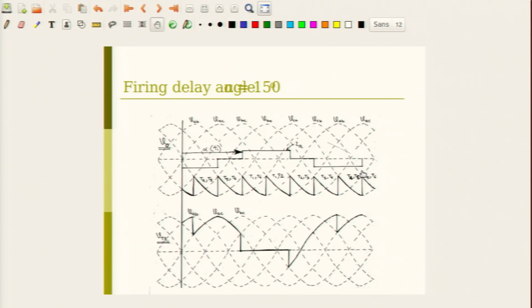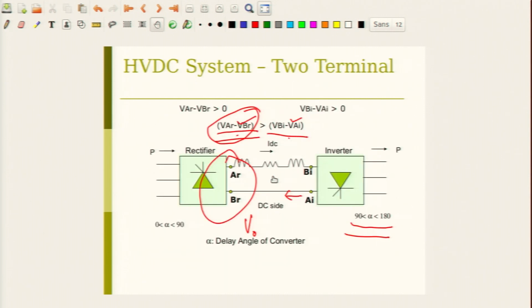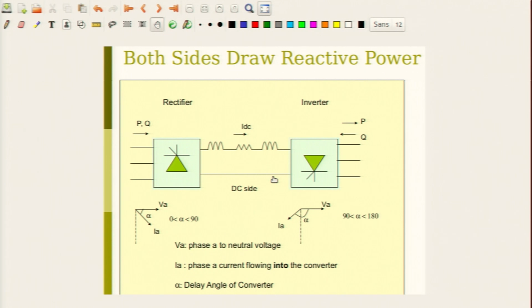If you notice these waveforms, all these thyristor switchings are orchestrated in some sense by the three phase voltages which are there on the AC side of that particular bridge. So, if you do not have AC side voltages, you will not be able to operate this inverter in the manner which I had mentioned. So, this is an important point regarding this line commutated converter based HVDC terminals.